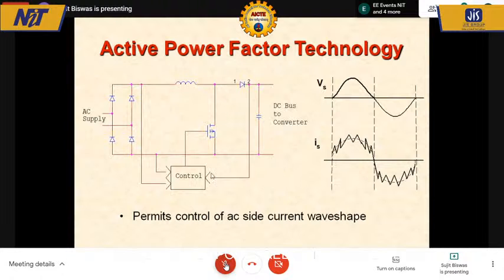So I use that information to increase the magnitude of my template of current. On the reverse, if the DC bus voltage tends to become larger than what it should be, then I reduce the template magnitude of the current. So the bus voltage monitors the magnitude of current and adjusts accordingly, so that we have the right balance and the voltage is maintained.